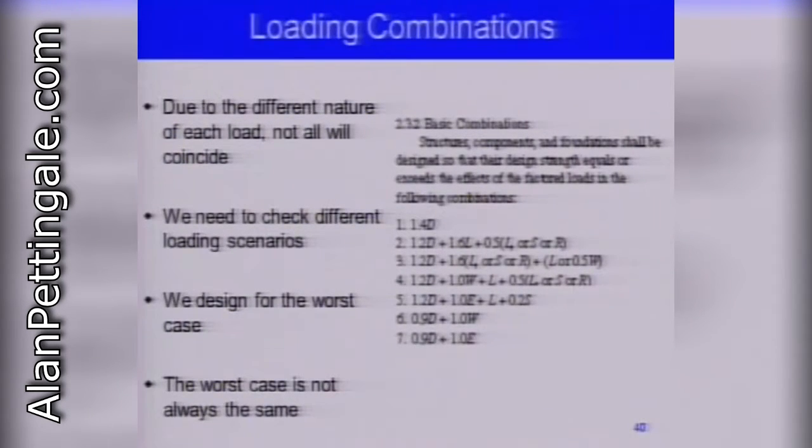For instance, in my class, I was teaching masonry last semester, and students took this load combination with the calculation of wind from the previous document. That's inconsistent, and that can lead to trouble because you really underestimate the load. So you have to pick a document, usually the latest one, and follow it throughout in calculating the loads and also calculating the factors that will be applied there.